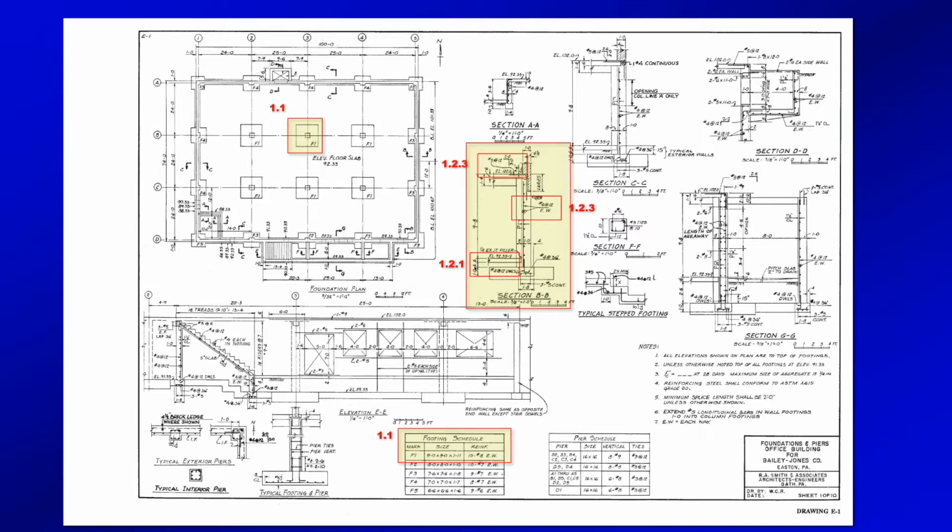But so what is the elevation? I say it's 91.33, and you could argue that pretty strongly, because it's very clear. It says per section BB. So you see it 92.33 minus 6 minus 6, so it's 91.33. How is the structure tied into the wall? So up here at the top, the structure is tied in with a number 5 at 12 inches. It's got a 2-foot hook and a 3-foot hook. I would suggest guys bring magnifying glasses with you too, because sometimes you can blow them up a little bit and kind of get a feel for it.